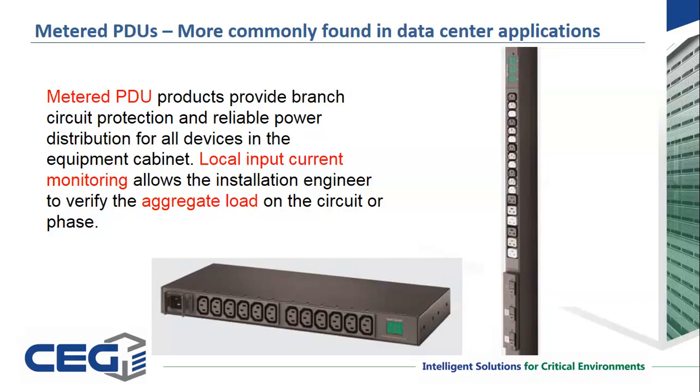But a meter on a power strip is an important best practice in most data center applications. And the meter provides the aggregate current draw. That's the total amount of current being consumed by this power strip. So that tells you if your strip is rated for a particular amperage, right? You've got a 20 amp plug feeding this thing. The last thing you want to do is plug a bunch of gear in there that exceeds 20 amps.